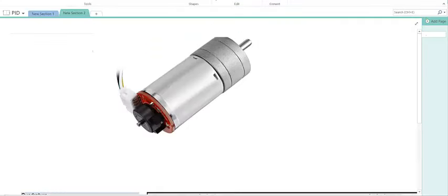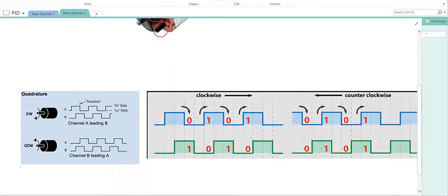Let's look at the encoder, how we're going to implement this in our code, and what exactly a control encoder is. So we're going to use a DC motor like this with the encoder attached to its back. And this encoder basically has these two sensors here. These are two Hall effect sensors, and there's a magnet on this black disc. When this shaft rotates, that disc and the magnet rotate around these two sensors and create square pulses. So there are two sensors that create two square pulses.